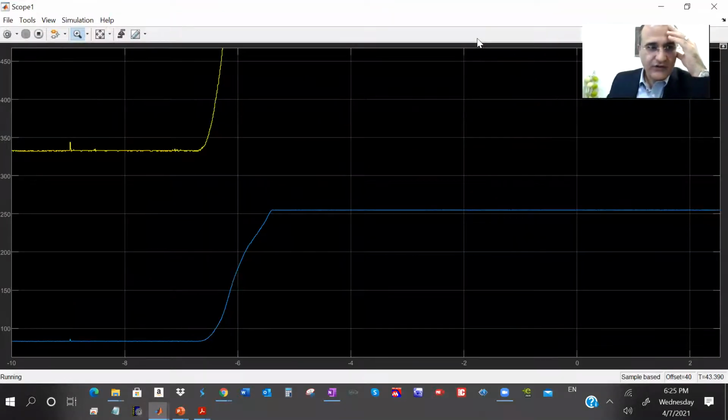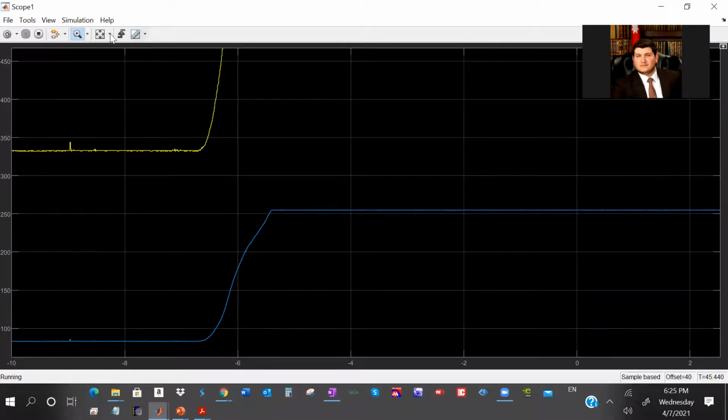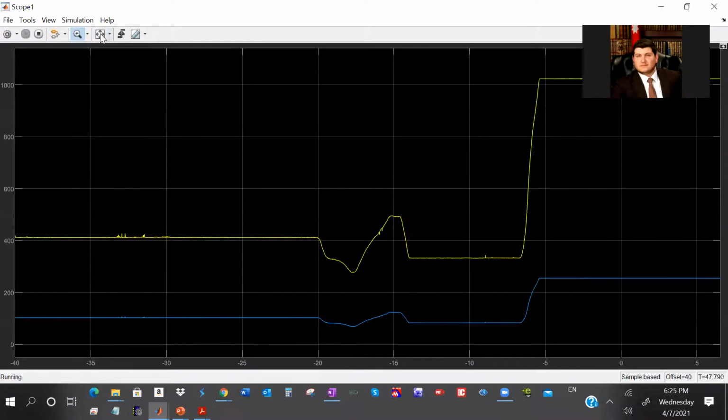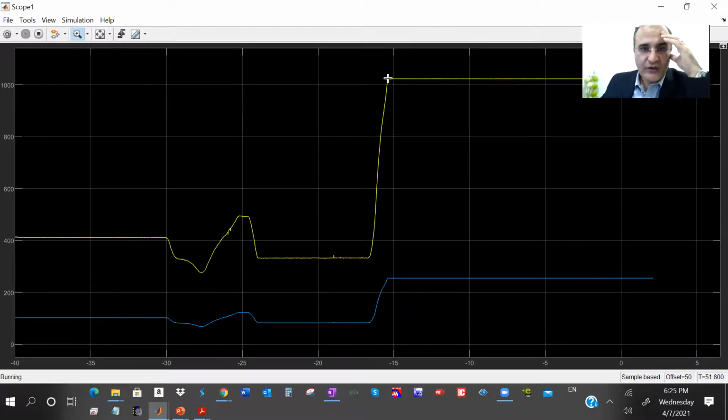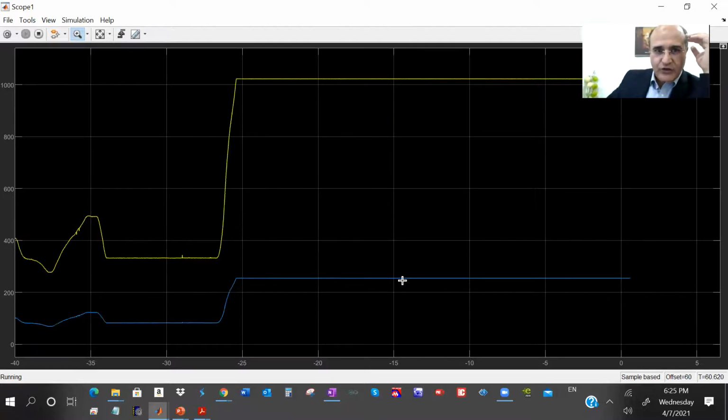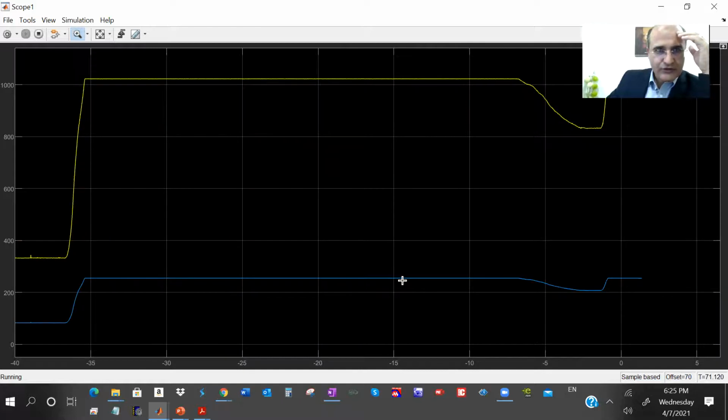You see my screen, right? Yes. And the yellow is the signal from the potentiometer. It moves from 0 to 1023, while the blue moves from 0 to 255. Now I'm going to start going down, but slowly, so you can see it going down. It's going to reach 0. I'm going to go up, then down, so you can see it on a new screen, a new iteration.